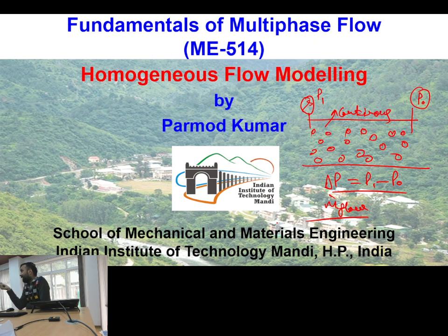I need to decide my pump, which will be able to meet these requirements. The second interest of engineers, which practicing engineers mostly achieve through experience, is to reduce the operational cost. For reducing the operational cost, they will try to choose a configuration of the pipeline such that they get the least pressure drop, so they invest a lesser amount of money on providing power to operate the pump.